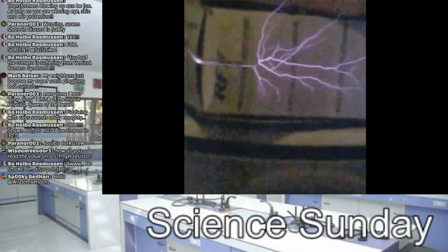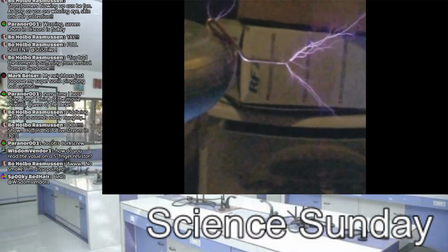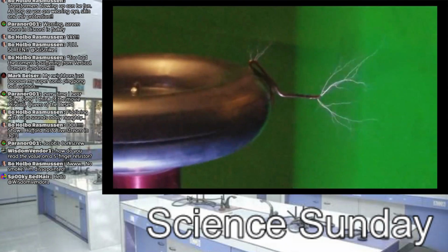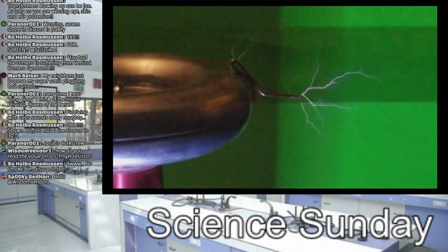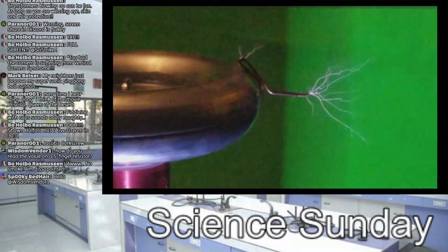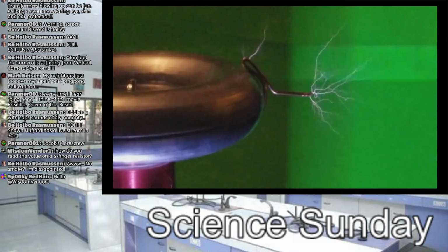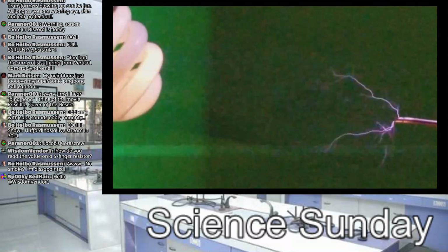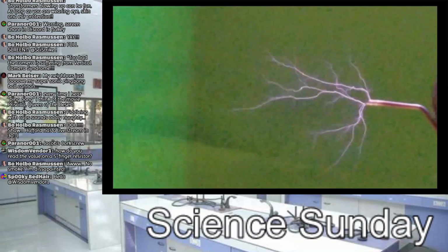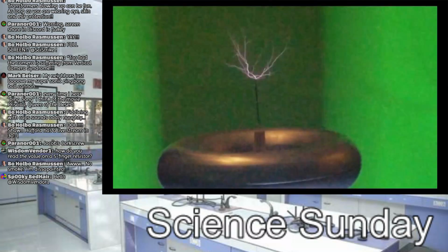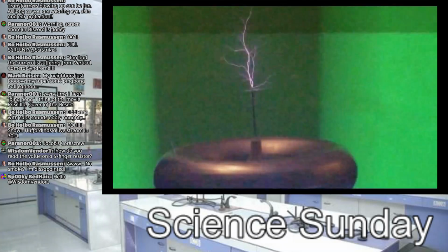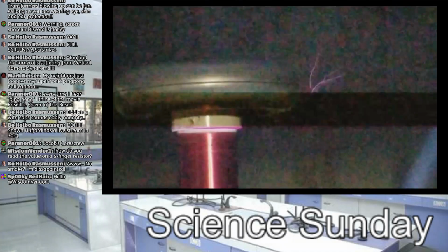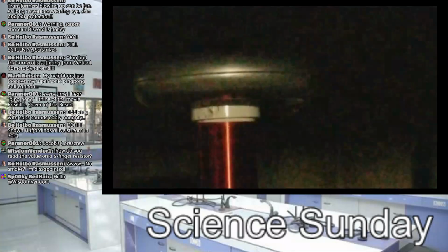Still thinking of making a breakout point like that. It's a good one to clip on, but when you finally get it to resonance with a smooth top load, it'll do a very interesting looking corona around the top. Now with the top loads, we both seem to have constructed exactly the same kind, almost as if I saw yours and said, "Hey, that'll work." But because they're not smooth, each of the ridges is acting as a rather inefficient breakout point. So without a sharp edge, we may not get a lot just from the top load.